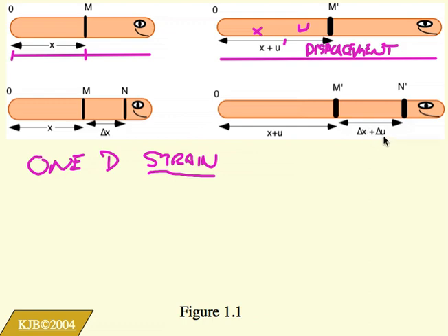If we use that description as our mechanism for describing the strain that takes place, we can write a strain, and in this case we'll write the strain as the letter E, but you'll also often see the letter epsilon, or similar letters from other alphabets, as being delta U over delta X. Or if we write this in terms of the conventional way to look at a line,